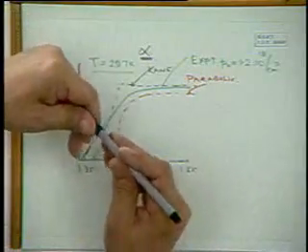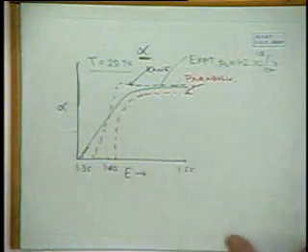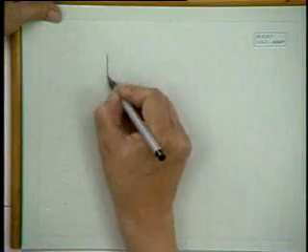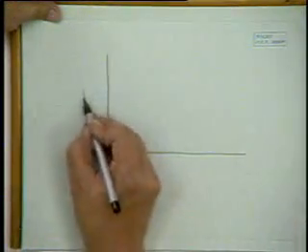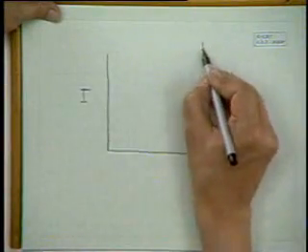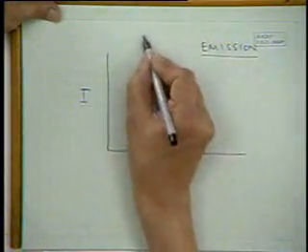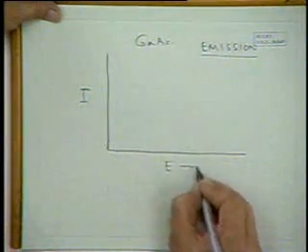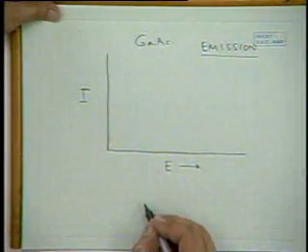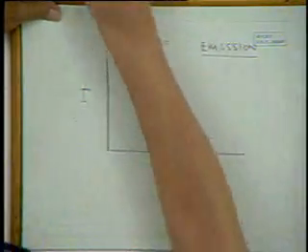Now, using the Van Roosbroeck-Shockley relation, we can go quite easily from this alpha versus E curve to theoretical determination of the relative intensity. Okay, that is absorption. Now we go to emission. Again gallium arsenide, 297 K. For parabolic bands, what do we get? Parabolic bands, extremely sharp.